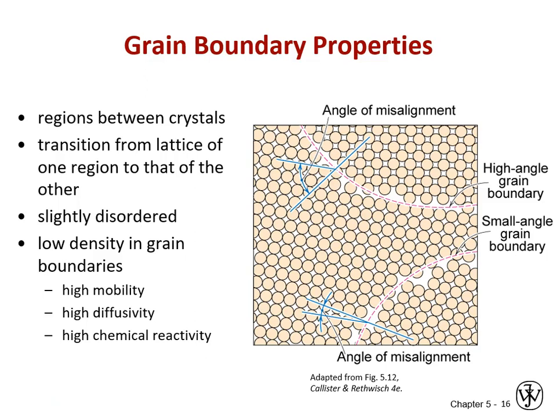If you're looking now at a cross section on an atomic level of 3 grains, and the blue lines are showing your close packed directions within each grain, the atoms are all touching in one grain, and then you move into the other grain and they're not touching, and that's because they're not oriented in the same direction. And so the higher the angle between those lines of close packed orientation, the higher the energy of the grain boundary between them. Along with being higher energy, because the atoms are on average further off their equilibrium positions, we're talking mechanical strain energy, elastic, coming from that non-equilibrium position in the potential well.